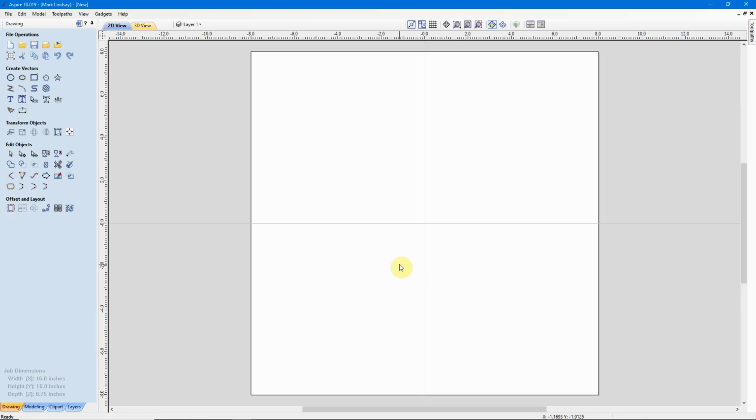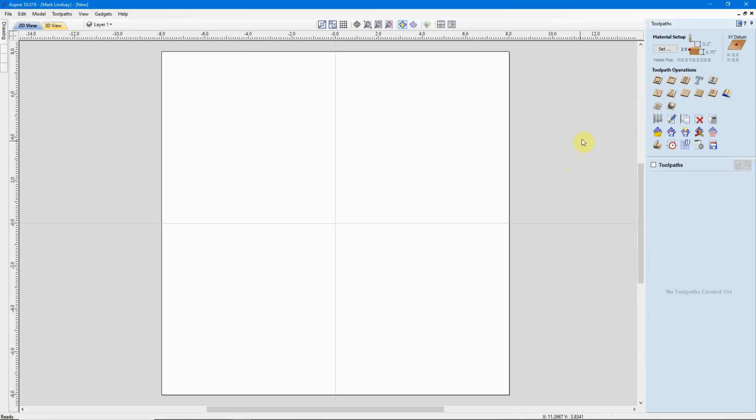Before we even get into that, let me just state that over here in the Toolpaths tab, if you're using a VCarve toolpath, a pocket toolpath, or a drilling toolpath, you will need closed vectors. But having said that, you don't necessarily need closed vectors to carve with a V-bit. You can use a profile toolpath or a quick engraving toolpath.